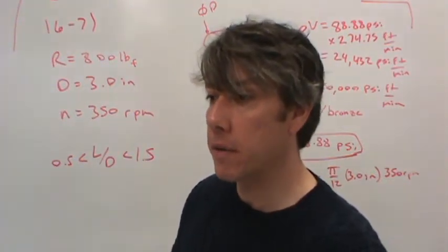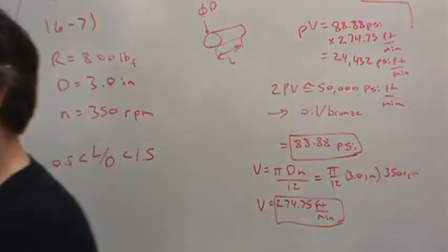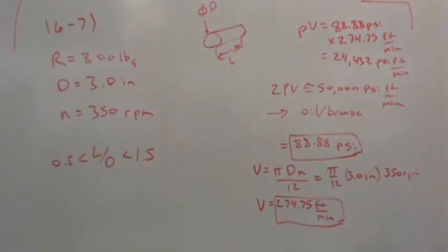Everybody understand where you got that from? There's a 3-inch bearing, this nominal diameter. If you go up to a speed of 350 RPM where they intersect, it's over a little bit because that 3-inch mark is to the right of the 75 millimeter a little bit. About 2.5 thousandths. Now what I would do, I would just bump that up to 0.003 of an inch and be done.